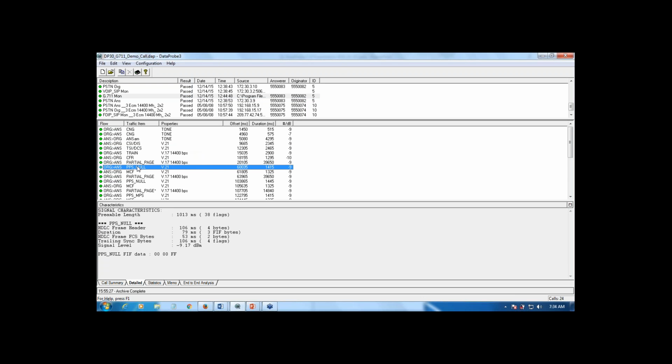And G.711 has this interesting dichotomy wherein it can either send you a stream of data, just one long round of packets of sound data, or it can send sound data and then silence, and then sound data, and then silence. And when it goes to mode number 2, it's a little bit of a challenge to directly recognize what the silence parameters are that are being specified in those packets and make sure that you get everything aligned again.